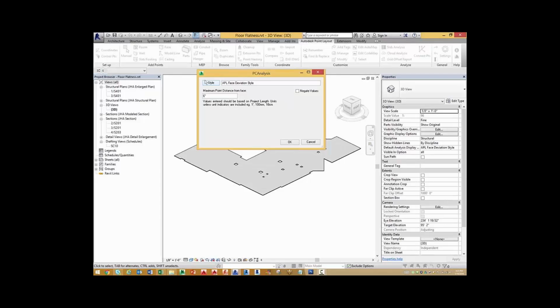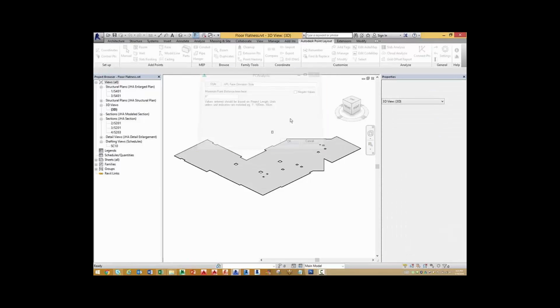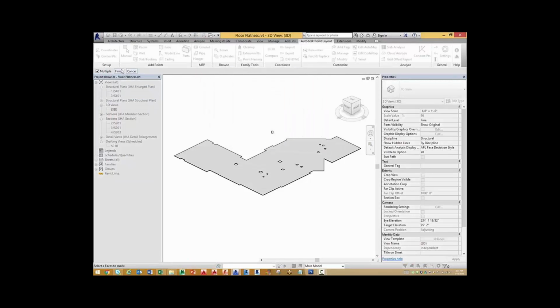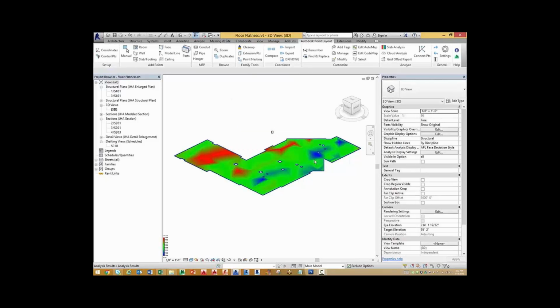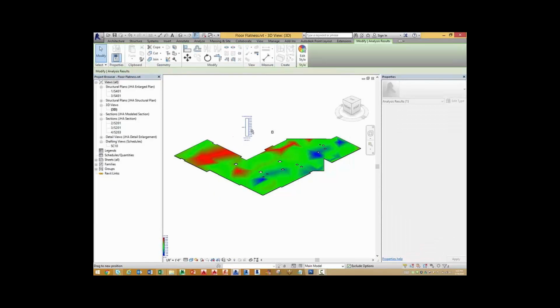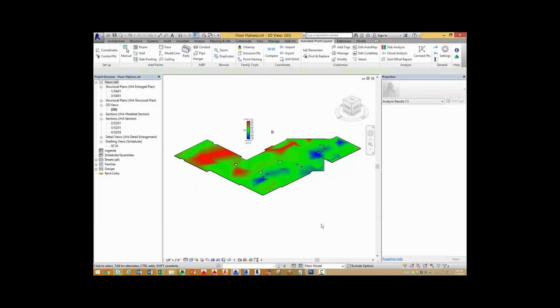When people bring in a point cloud without controls, they move it manually, and then they have to adjust it vertically. Well, how do you know exactly how high to lower or raise the point cloud? Well, if you use the GLS, where it knows how high it is off the ground and where it is in space based on control, now when I bring it in, I can get a quick analysis of that floor slab and see how flat it is.